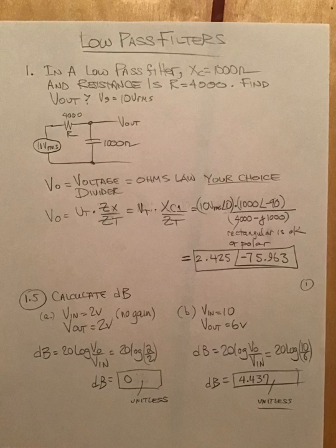At this point, this kind of problem should be on your hit list. This is just a problem with two components, and a voltage divider will set you up. You're trying to find the voltage out, given that you've got all the impedances and all the voltages, and that's an easy voltage divider thing. Did we have to? No, we could have used Ohm's law too. You would have had to get ZT and then go get IT, and then you could have found what V out would have been after that. Maybe you try that to see if it works, okay?